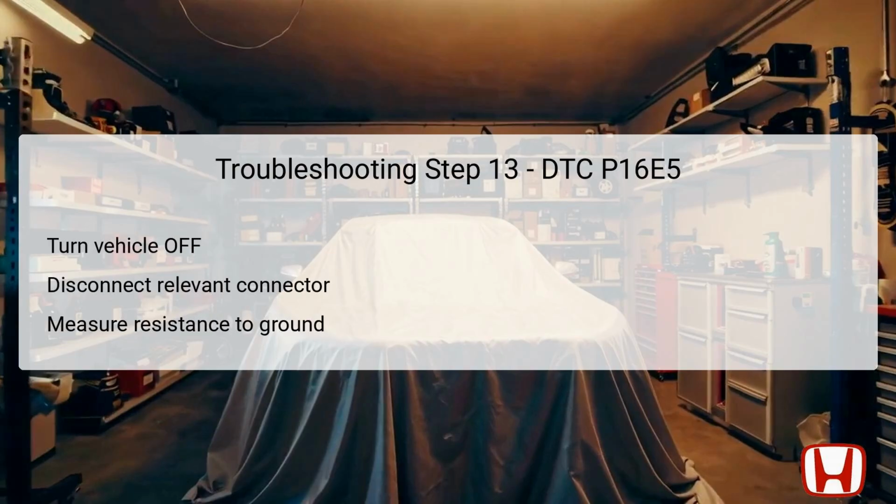Reconnect the DC-DC converter connector A after verifying earlier checks. Then, proceed to disconnect the relevant connectors to measure the resistance accurately. Measure the resistance between the test points, keeping an eye on ensuring it reads 1 megaohm or more, signifying sound wiring integrity. This audit indicates whether the LIN bat sensor, LIN line, connects correctly, impacting any further analysis. If the test does not pass, the investigation should continue toward identifying shorts or breaks in the wire connections.